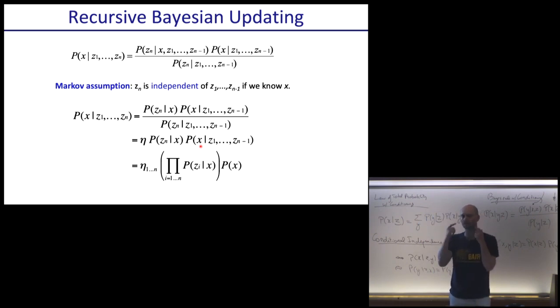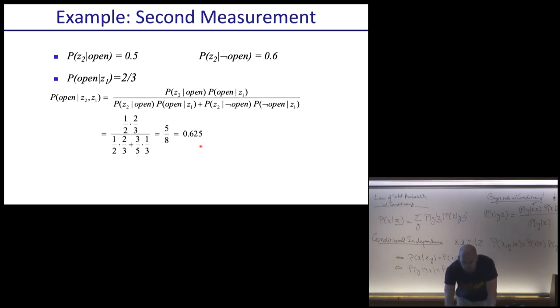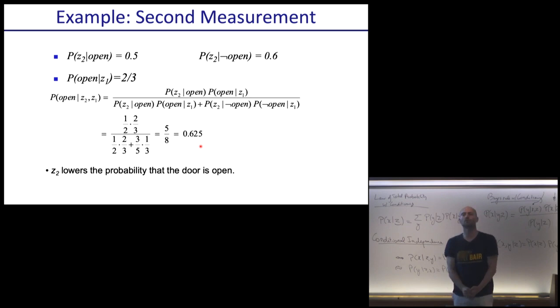You need to think carefully: are these sensory readings really independent? Or imagine a laser rangefinder is reading something at time t, and you run it again at time t plus 1, but nothing has changed in the world. Then are those really independent readings? Not necessarily, because you're measuring the exact same configuration with the exact same sensor, so maybe it's not completely independent. So be careful. What can the effect be? Imagine you think these readings are independent, and they're not. What do you think will happen?